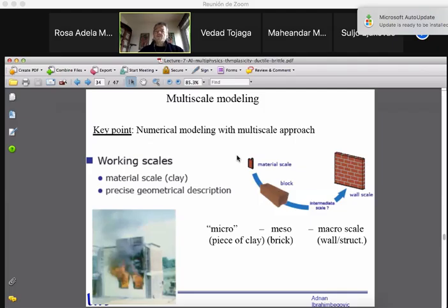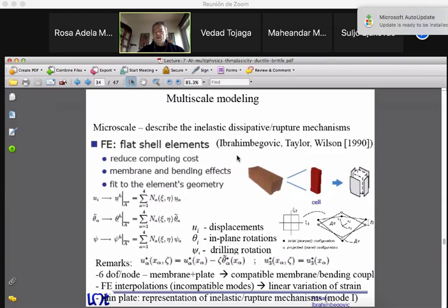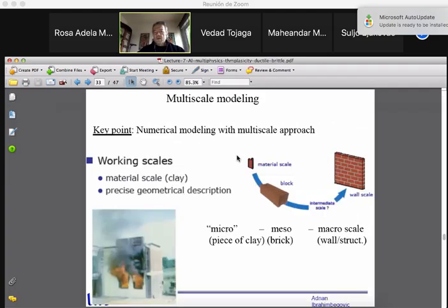So the way it worked is the following. First of all, you had a particular structure of this block, and it turns out that this block, when you look at how it is working, is a part of the wall. So the wall is exposed to fire. Down in the basement, it is built in. It cannot deform. But the fire on one side makes the temperature gradient go in the horizontal and vertical direction. So the wall will bend both in the horizontal and vertical direction because of the temperature, heated on one side and not on the other side.